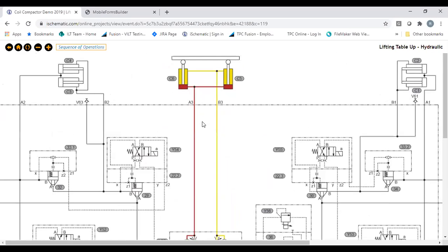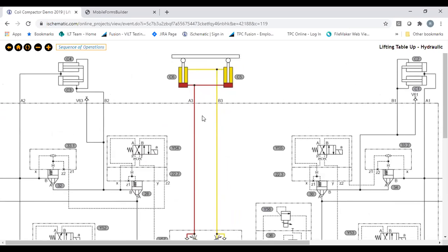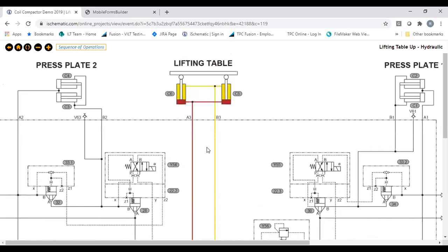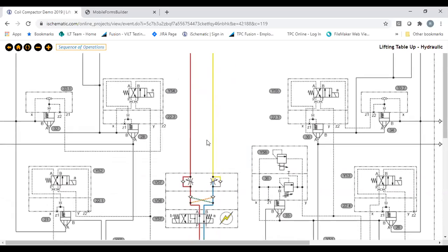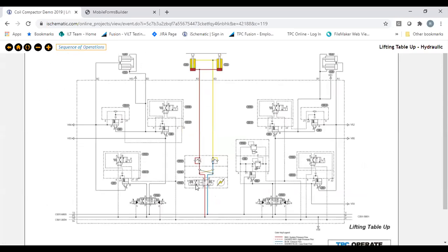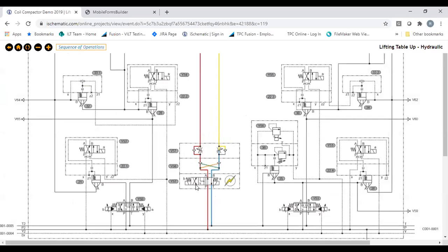So, I was describing it to you verbally, but within what, 60 seconds, 30 seconds, we got a short list, like we talked about, for troubleshooting: the short list of components on the table. These two lifting cylinders, this pressure regulation or these flow regulators, these flow controllers, this counterbalance module, and the solenoid valve.